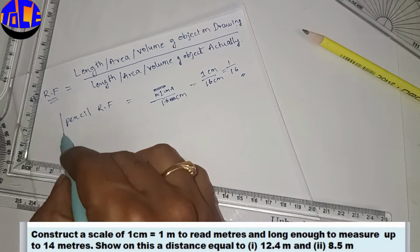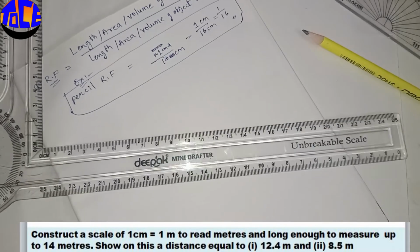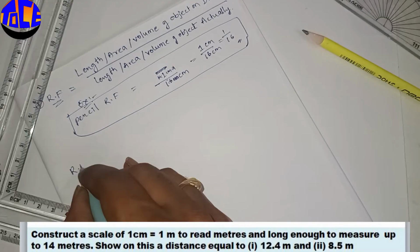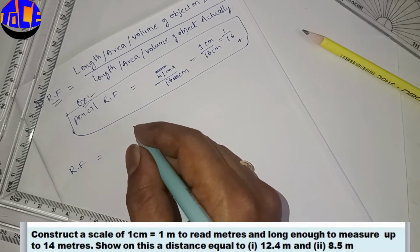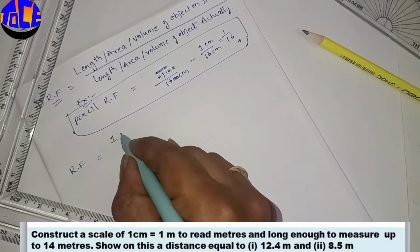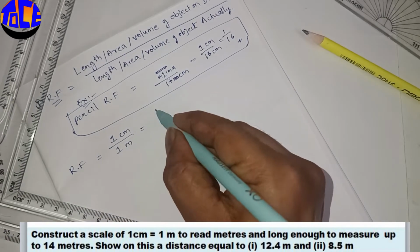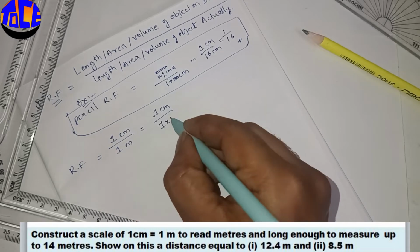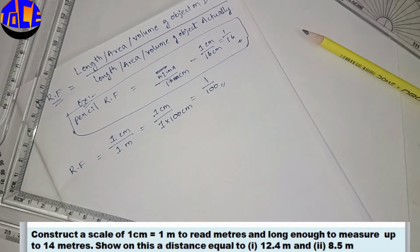Okay. So similarly, for the given question also, we need to find out. This is just an example to understand what is RF. So similarly, for the given question as well, we need to find out what is RF. Here in the question, it is mentioned that 1 centimeter is equal to 1 meter. So 1 centimeter on the drawing will be equal to 1 meter of actual length. So 1 centimeter will be in the numerator and in the denominator 1 meter. Both the units should be the same, so I will convert the denominator into centimeters. 1 meter is equal to 100 centimeters, we know that. So it will be 1 by 100. So we got the RF value.